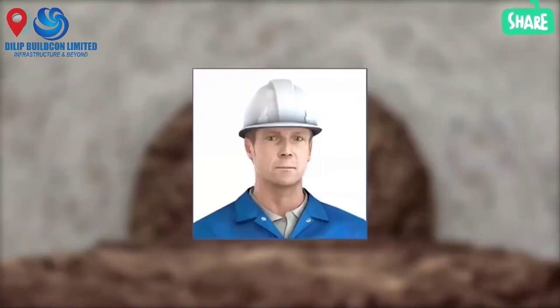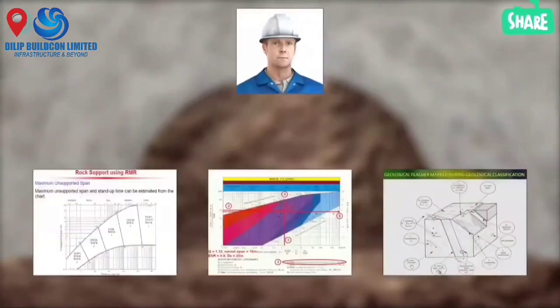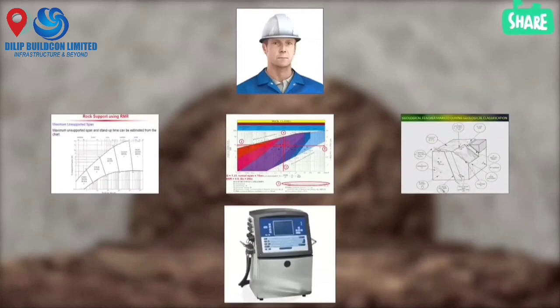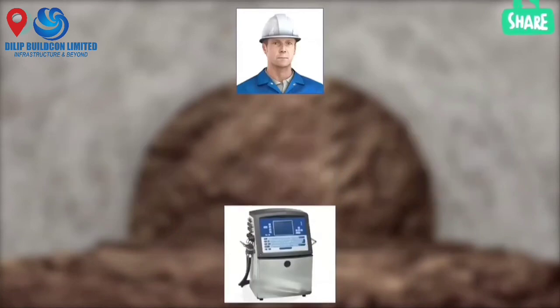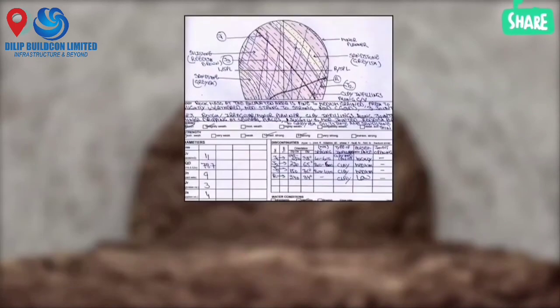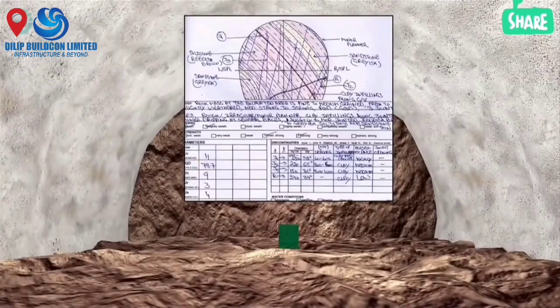Geologists and surveyors analyze the class of rock after every round of blasting operation and find the Q value and RMR value. Depending on the class of rock, the rest of the tunneling steps to be undertaken is formulated. Geologists and surveyors collect data with the help of a profiler machine and plot them on paper. Charging patterns change with change in rock class.